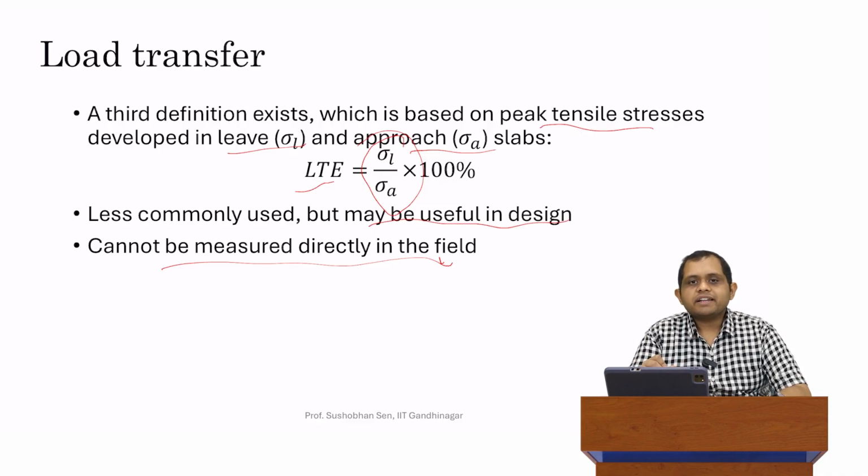When you're doing design, for example, when you're using Westergaard's theory and calculating stresses, and you're interested in accounting for load transfer, in such a situation you might be particularly interested in using a stress-based definition or maybe even a load-based definition. Indeed, when we go into a little more detail on analysis of dowels or dowel systems, we will see this sort of definition coming back. But beyond design applications, and even that is not used too much anymore as we've gone to using finite element methods, this equation is not particularly useful.